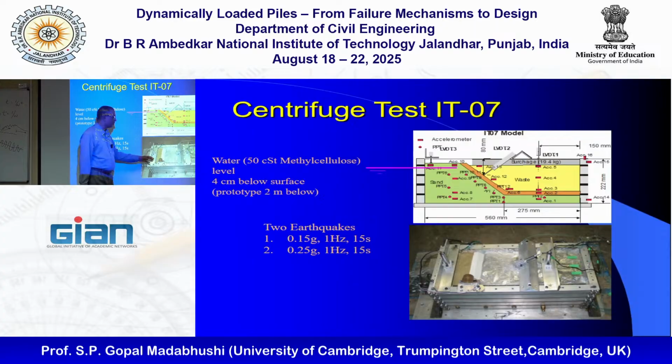This is good 25 years ago. He had like a webcam which is looking here because we're expecting to see liquefaction at the back. So that's the cross section, that's the real model. Very easy to understand. We also had other tests where we were looking at the tension in the geomembrane.